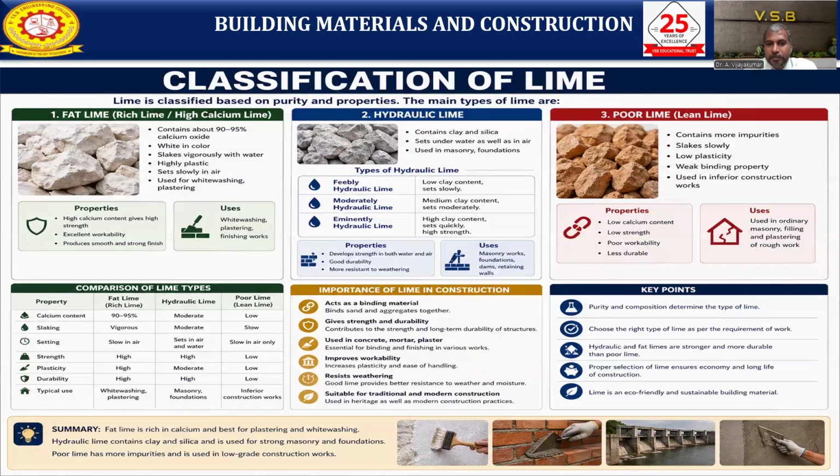Lime is used in concrete, mortar as well as plastering purposes. It is essential for the finishing of various works. It improves workability and resists weathering action. So it is suitable for traditional and modern construction purposes. That's why we also use lime for heritage structures.